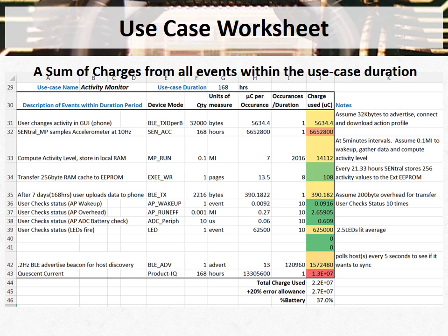The cells highlighted in green have the lowest charge consumption, and the cells highlighted in red have the highest. Charge is the common unit of measure and is directly related to the power source capacity. Actions on this worksheet include data transfers, constants, quiescence and sleep currents, instruction executions, and user events.